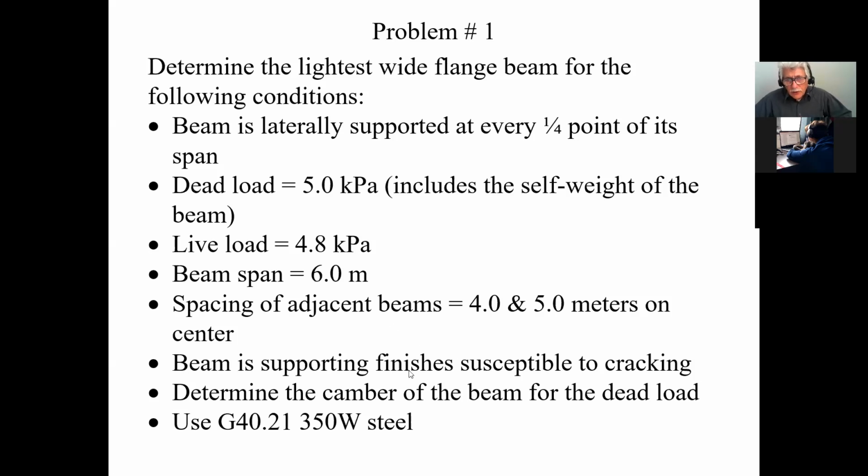Now, the beam is supporting finishes susceptible to cracking. What this tells you right away is that your deflection criteria has to be limited to L over 360 minimum if you want to minimize the effects of the deflection on your finishes. Then you want to determine the camber of the beam for the dead load. So once you've designed your beam, all you've got to do is calculate the dead load deflection. You'll know how much camber you can ask the fabricator to do.